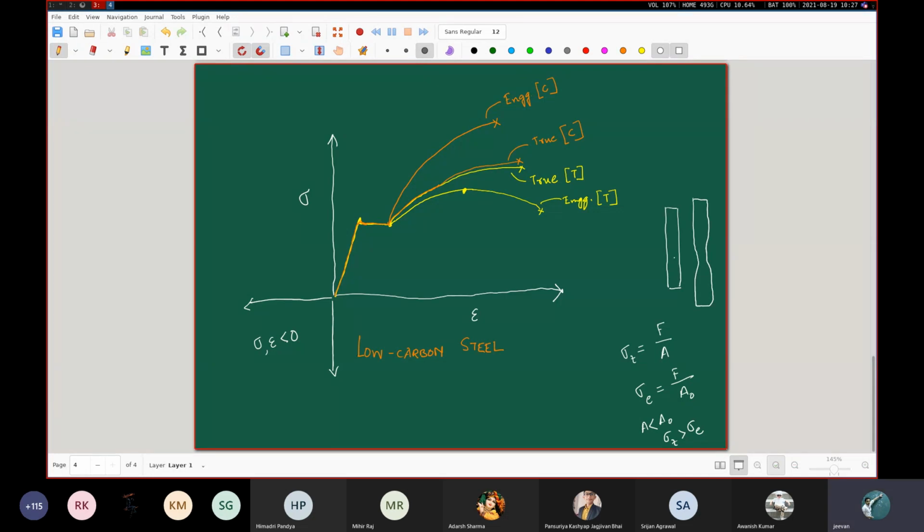On the other hand, if you try to push against the two edges of the paper, now for a paper, it doesn't make too much sense to talk about compression because it doesn't support compression very well overall. But suppose you have a thicker piece of paper like a cardboard piece, and you have a perforation in the middle, and you are trying to push against the edges, it will be able to maintain its structural integrity, or in other words, it will not tear under the action of those compressive forces. So it can sustain higher forces and consequently higher stresses. That is also one of the reasons. The two reasons that we have discussed are not exclusive in nature. They work together hand in hand along with a number of other microscopic reasons. As a result, the stresses that appear for this compressive diagram are much larger than for the tensile.